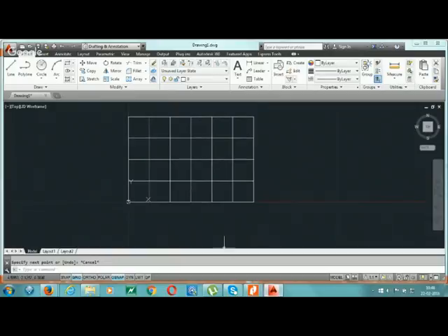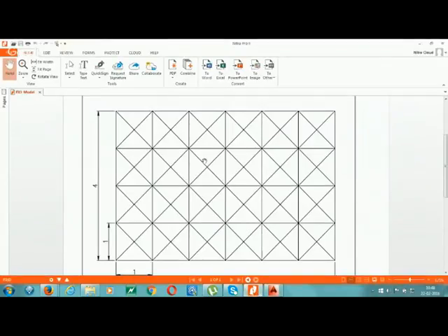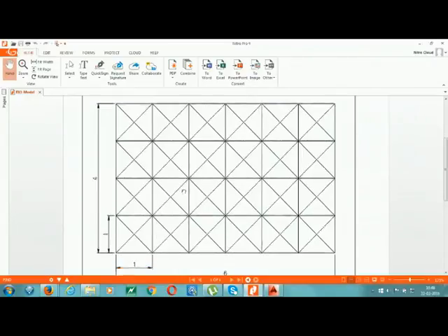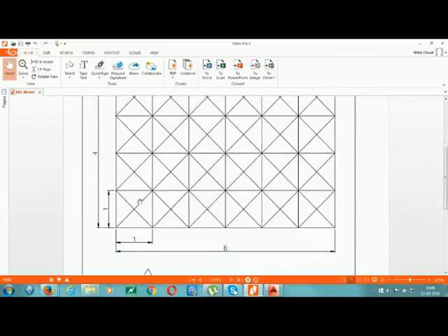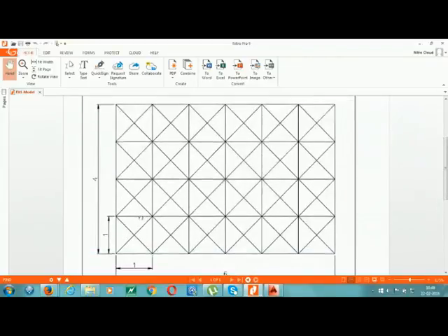Now we have made the diagram's vertical and horizontal lines. Now we make the angle lines with the help of the absolute coordinate system. First make this line: the starting point is 0, 0 and the end point is 4, 4, since it goes 4 in the y direction and 4 in the x direction.